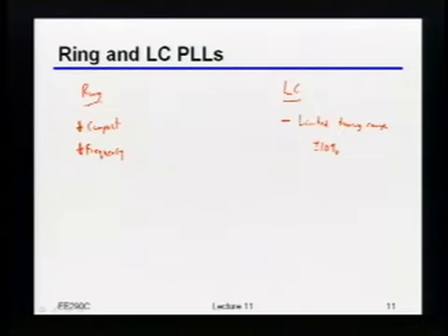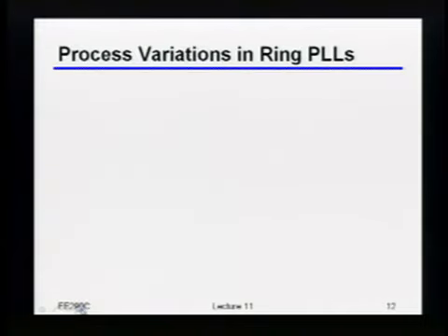Okay? But now, just to give you an idea, roughly speaking, you can easily get, well, maybe that's a little bit aggressive, but not too uncommon, about a factor of 2x range in that ring at a fixed voltage. If you start moving the voltage around and the process and the temperature, you can pretty easily end up with 3 to maybe even about 10x range of things that ring might be dealing with. This turns out to have some pretty interesting implications in terms of how you'd actually want to build the PLL. So let's think about that a little bit more carefully.